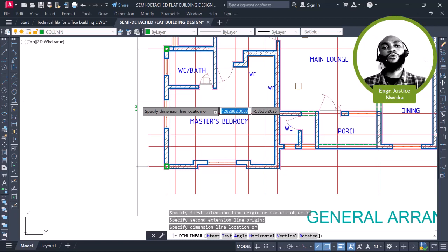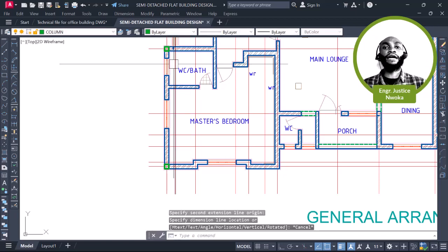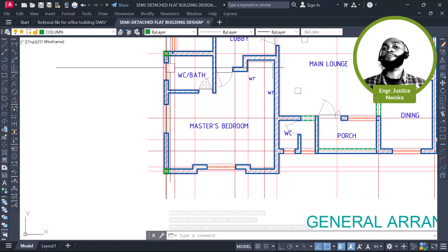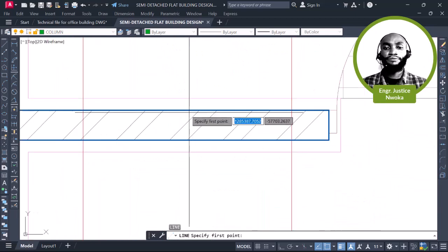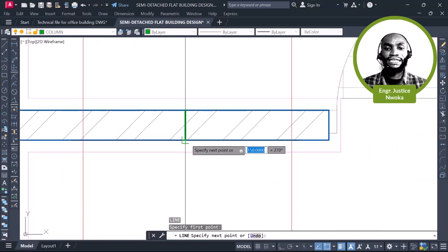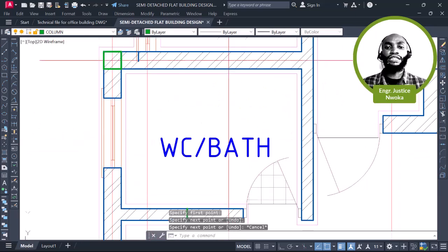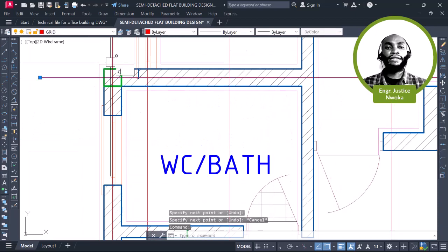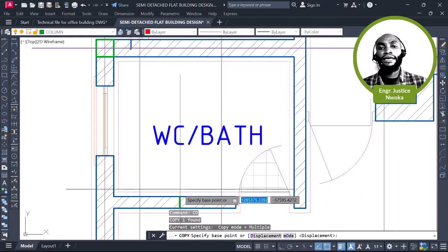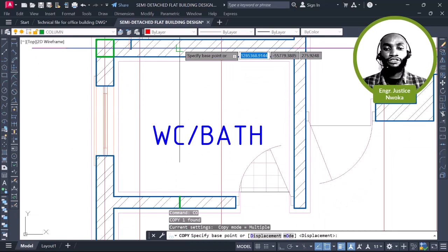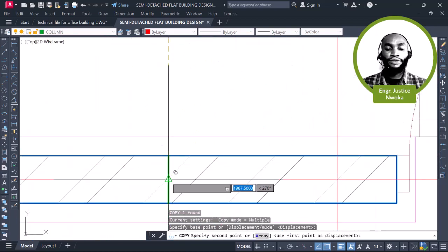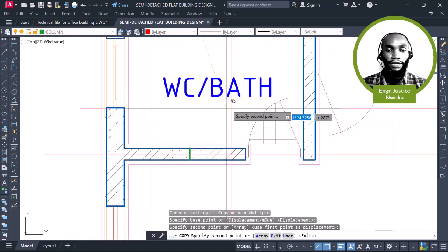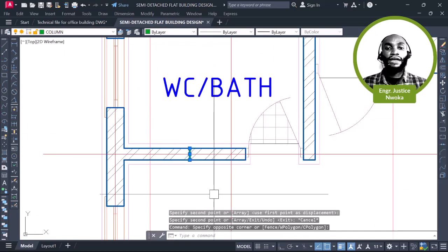To place a column there, which will be cheaper compared to increasing the beam depth and also using a bigger diameter of bar. So with that, I'll now divide this line into two first to get my grid lines. I'll click on this grid line and use a track to track this from here to here, and then place this at the middle here. That's fine, and remove this immediately.